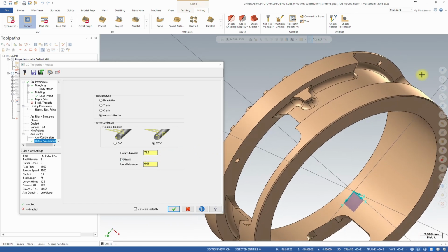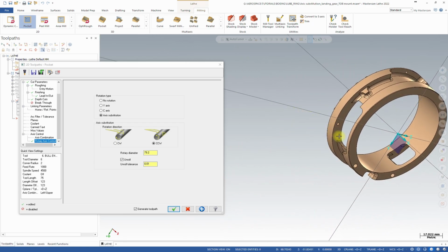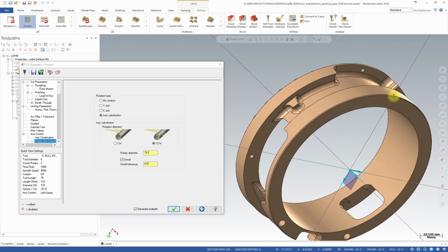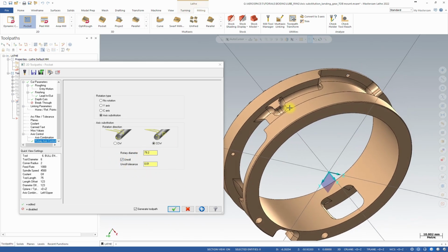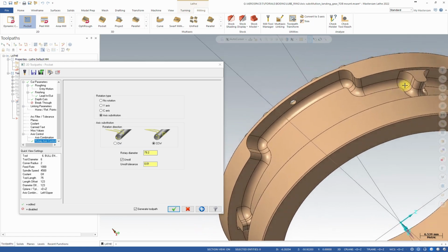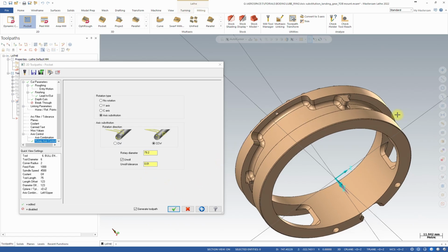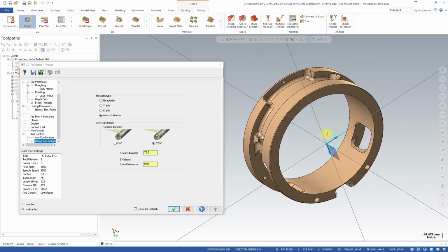is because our chain is located on the 3D model on the diameter, on the rotary diameter that we actually selected. And Mastercam, for some calculation purpose, needs to unroll it to make it flat, and then when it's rolling it back into diameter, it replaces the motion y-axis with the rotary axis. And again, you have to tick unroll if you select your chain like me on this diameter, around the diameter. You don't use it only when you throw 2D pocket and roll this pocket onto the diameter. And here, as I mentioned, this is the diameter where your chain is located.